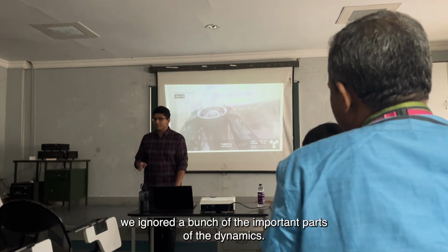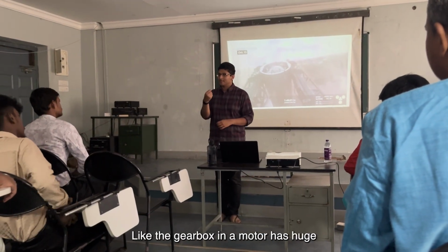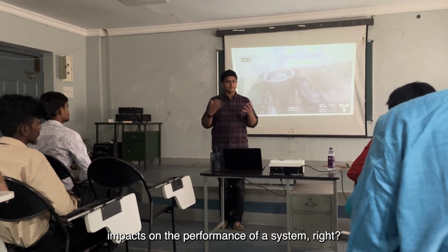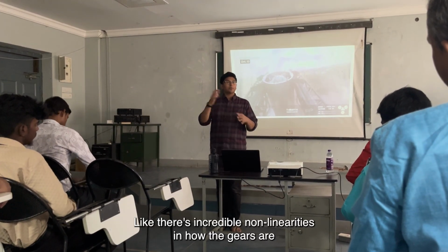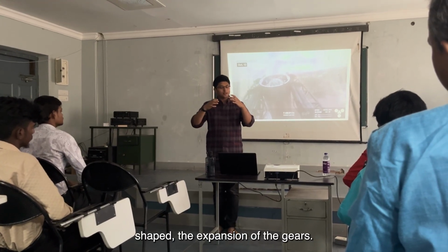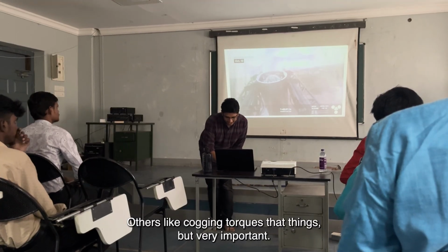And in this setup, we ignored a bunch of the important parts of the dynamics. Like the gearbox in a motor has huge impacts on the performance of a system, right? There are incredible nonlinearities in how the gears are shaped, the expansion of the gears. There are cogging torques, like crazy things. They're very important.